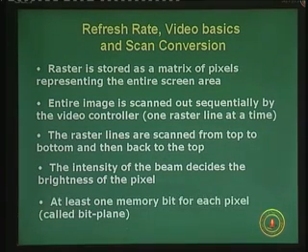Well, we have at least one memory bit inside the frame buffer, which could be a part of the system memory or it could be a part of the video controller. We will see that, but essentially when we talk of the adapter cards, typically they have a video RAM inbuilt in the card along with the video controller which drives the monitor, but some part of the frame buffer could be in the system RAM or it could be in the video controller.